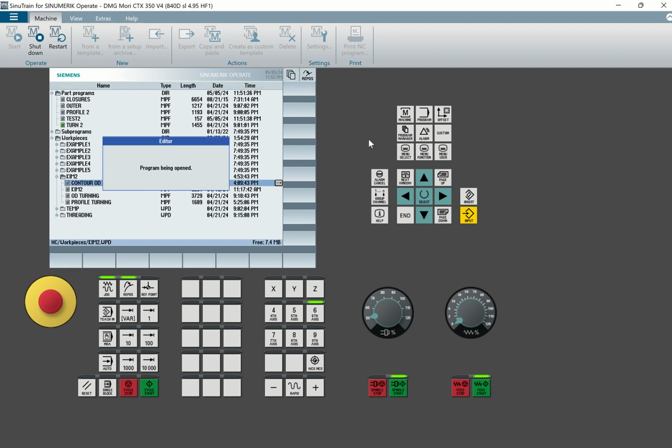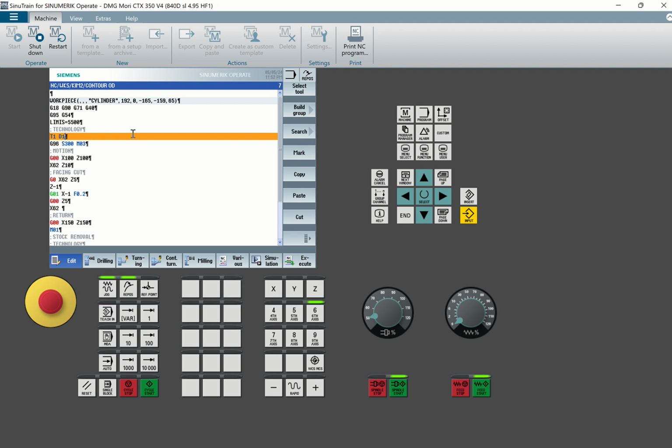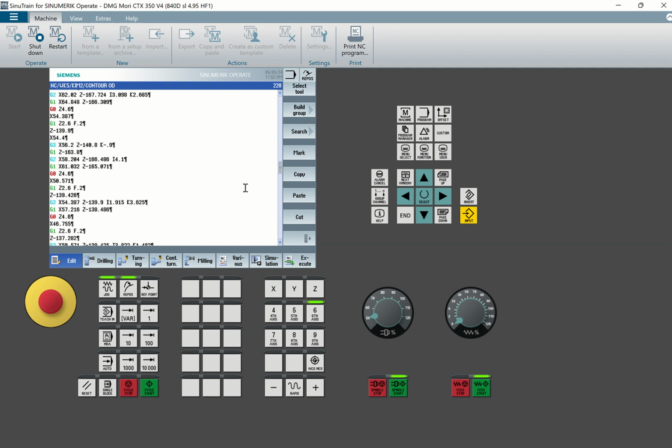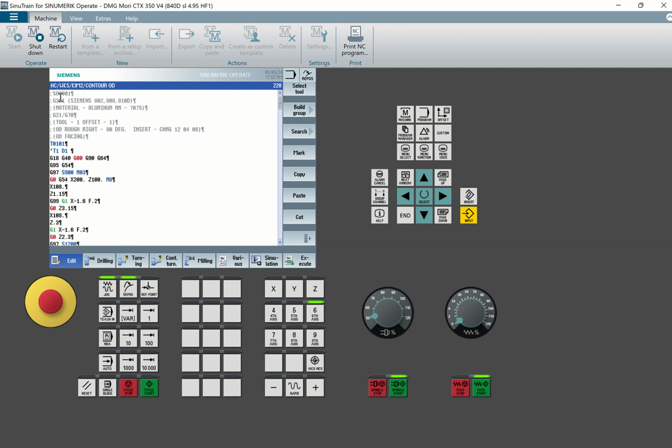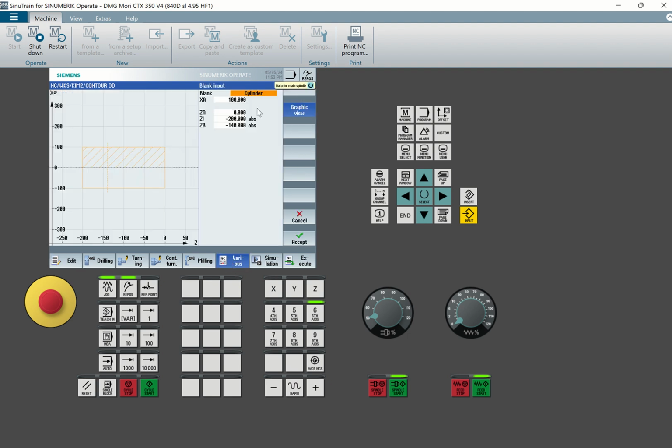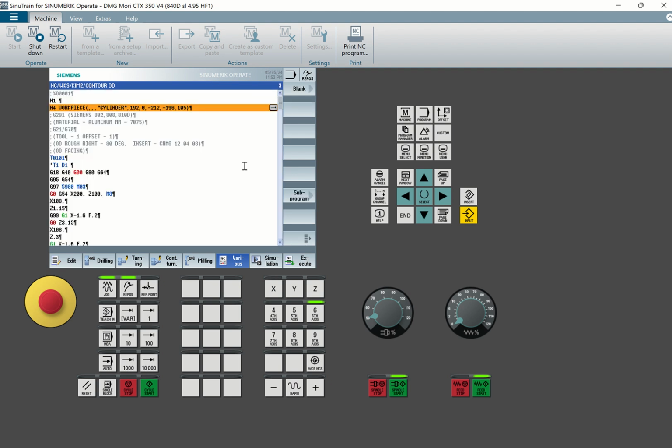Expand this and this. I want to change all here, all of them. Cut. Paste this. I want to test this. It will give me whatever I want. Then here, let me put my stock so I can come to variable blank. Then here, the largest outer diameter is 105, so it's minus 212. Then it's clamping at -20, so it's 176. Okay, then accept. So that's my stock.